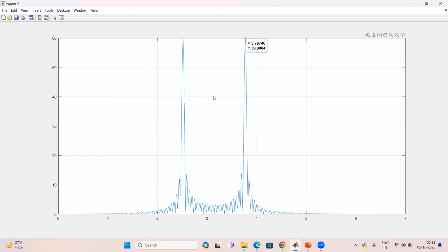In the pass band, the attenuation of the signal will be very small, but in the stop band, the attenuation will be larger. Within the transition band, it will allow a certain amount of signal to pass through. Therefore its magnitude gets reduced, but it is not completely removed. By proper care in designing the filter, we can easily remove this component.